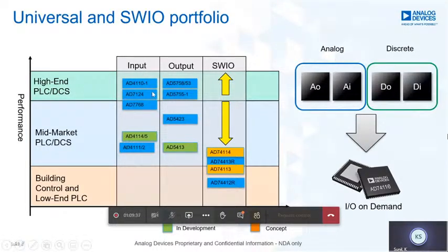We are talking about a combination of input devices, basically precision ADCs and precision DACs with a very high level of integration to bring in that software configurability on the input side. Likewise, on the output side, precision DACs with configurability to give either current or voltage output, which can be configured through software, or I/O systems which bridge the legacy to the modern T1L systems with that configurable I/O, a mix of products with different channel counts.